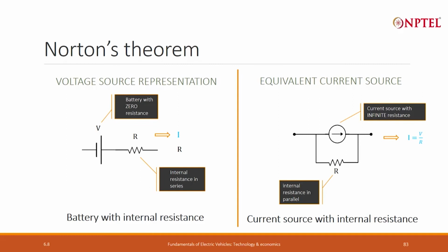transformation is that when we look at the thermal flow, for example, there is copper. I know how much heat is getting generated, the Q. The Q is known, I squared R, but I do not know what is the temperature difference. That is something that I am yet to find out. So, I would rather model the copper winding based on what I already know, rather than model it based on what I do not know.